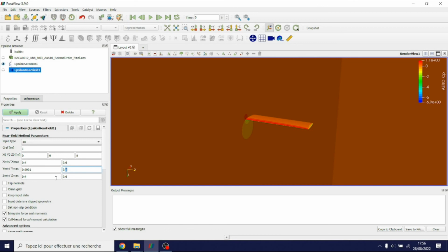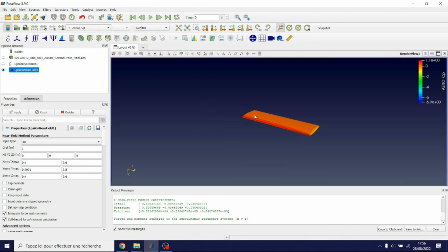So it is predefined like this because if your CFD domain lies on the positive y-axis, it will work as it is by default. So if you apply by default, it will take away the geometry instantly. Just keep in mind that if you change that to 0, in some versions of ParaView it might include the external surface, a part of the surface lying at the symmetry plane, which is undesirable.